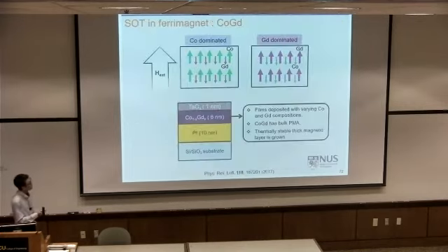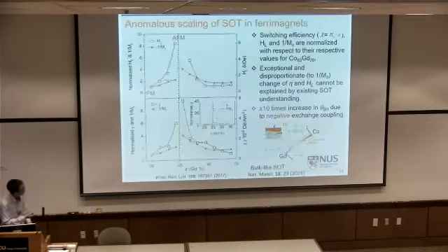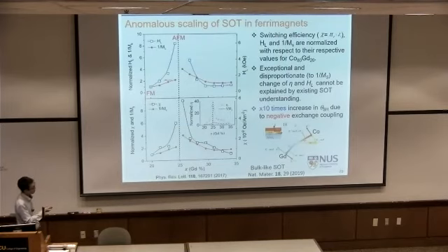The other one I want to introduce is the ferrimagnet. Professor Lee also showed that ferrimagnets can be very interesting for skyrmion or domain wall motion, but we utilize this one for spin-orbit torque switching. This material can easily be grown like a bulk PMA, very thick. In this case we use 6 nanometers, but you can easily grow 20 or 30 nanometers of PMA, no problem. And we use a platinum underlayer, and we can study it as a function of gadolinium composition.